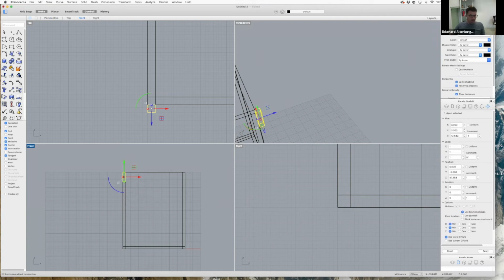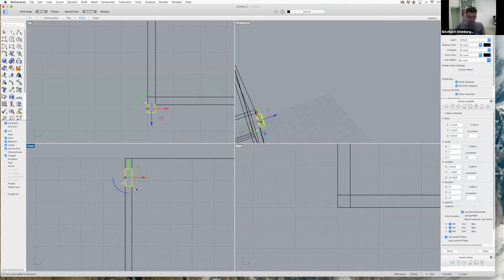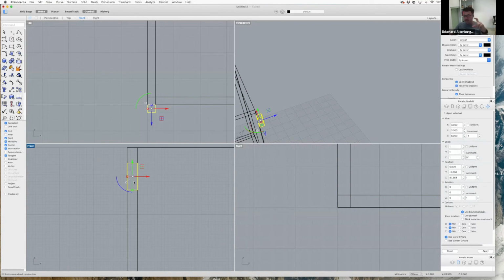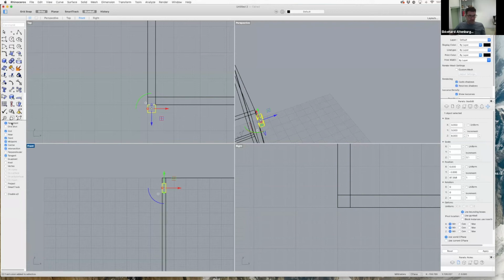I think we make it slightly shorter. So this is at the moment 12 millimeters long. Let's make it 8. I could calculate the exact size now, but I'm just guessing at the moment. So at the moment, I have a little box that is 8 millimeter high, 8 by 3 by 3, yeah? And I need 6 of those. You could copy and paste, copy and paste, copy and paste, but that's far too complicated. You can use the command array.